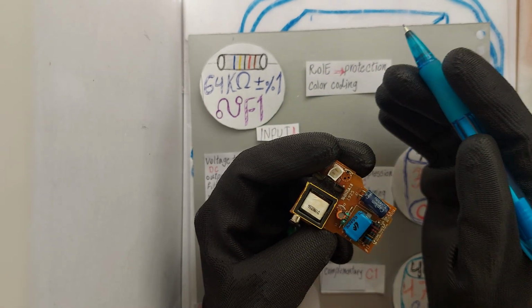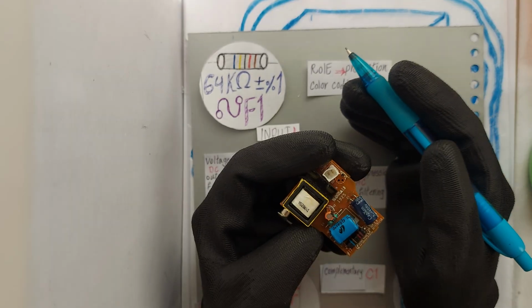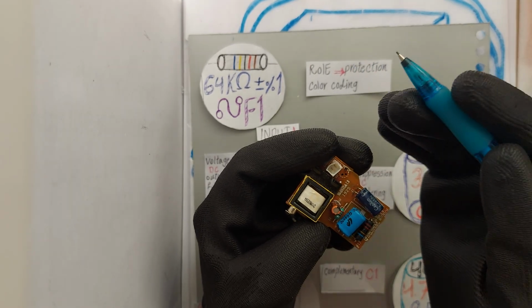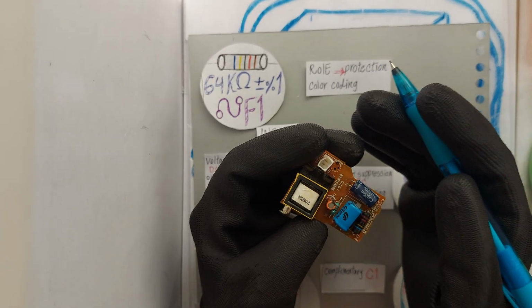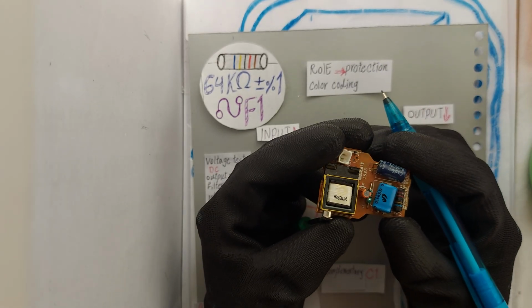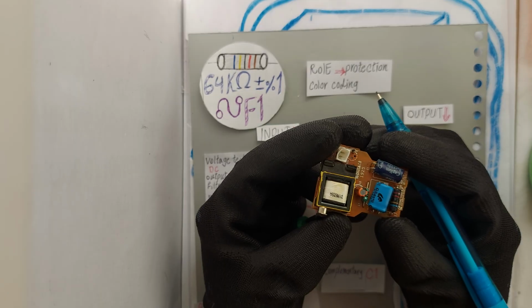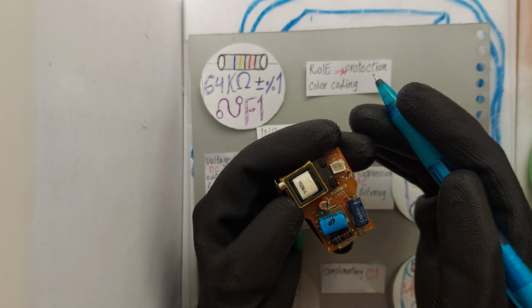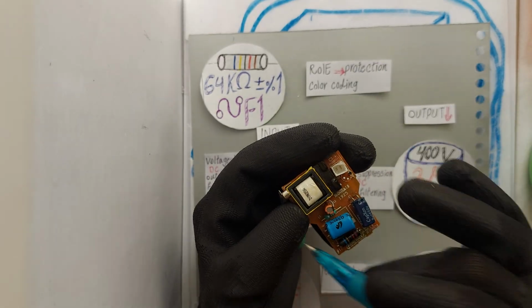It acts as a protective component on its own. It combines a resistor and fuse. It functions as a resistor under normal conditions, regulating current. If the current exceeds the allowed limit, typically specified in the datasheet, the fuse blows or opens the circuit, preventing damage to other components. Role on the board.